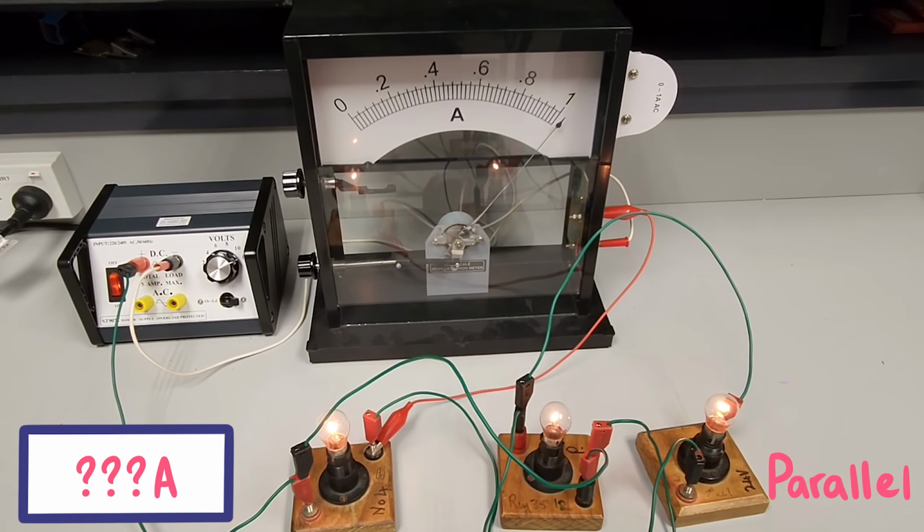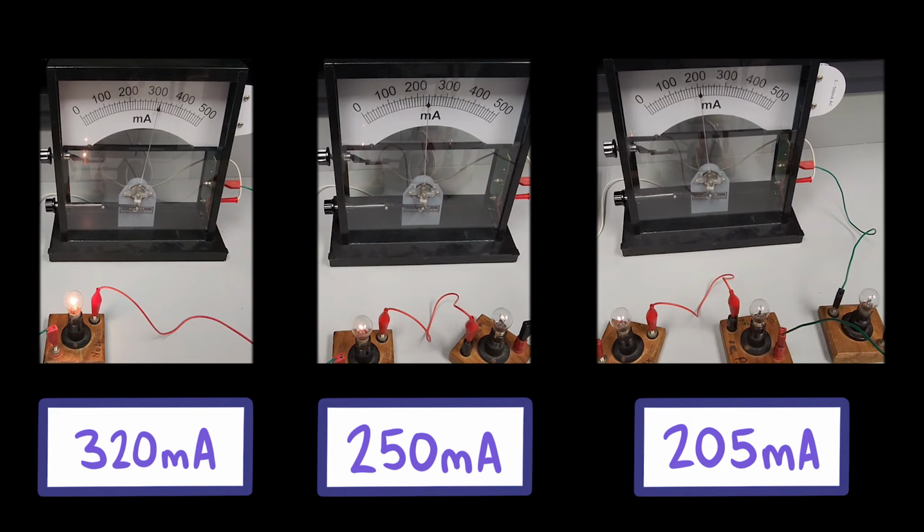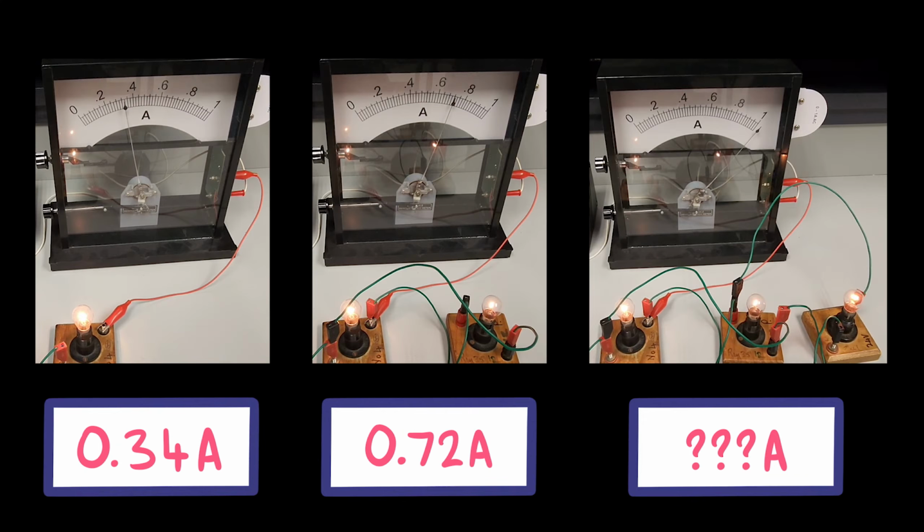To summarize these experiments, adding bulbs in series increases the resistance and reduces the current. This happens because the bulbs share a single pathway, and each added bulb increases the resistance of that pathway. For our parallel circuit, it was the other way around. For each added bulb, the resistance decreased and the current increased. This happens because each added bulb is added on its own pathway, with a resistance and current that is independent to the others. And so our total current increases because there are more pathways through which it can flow.